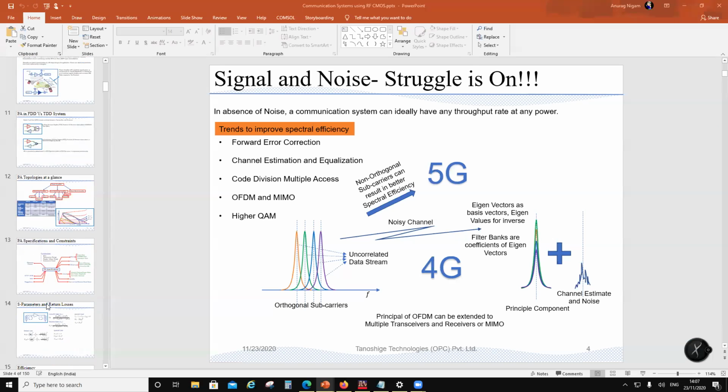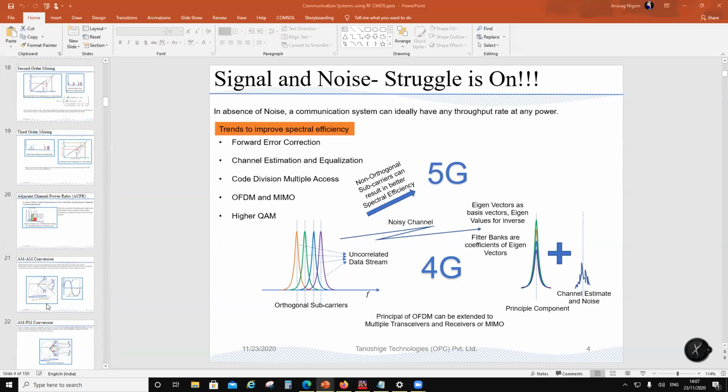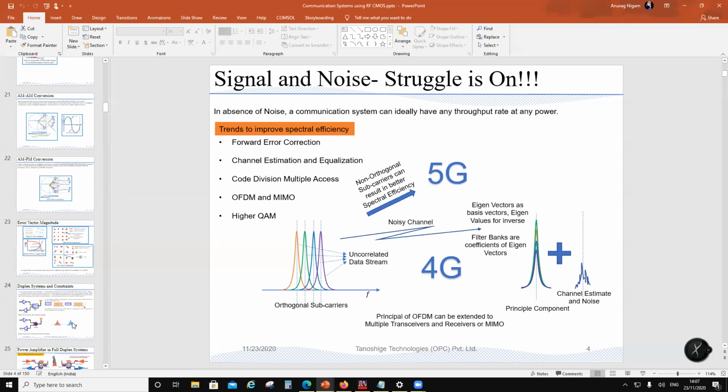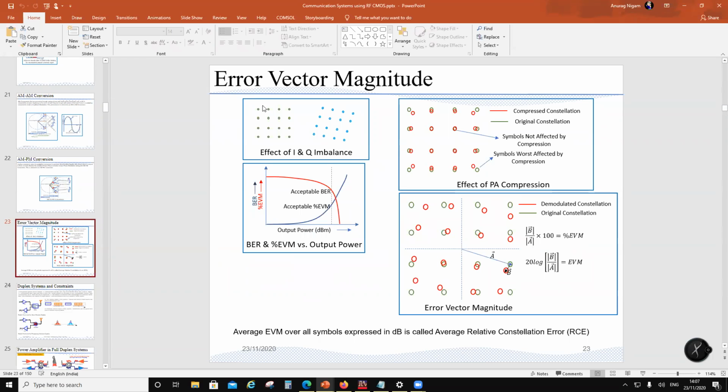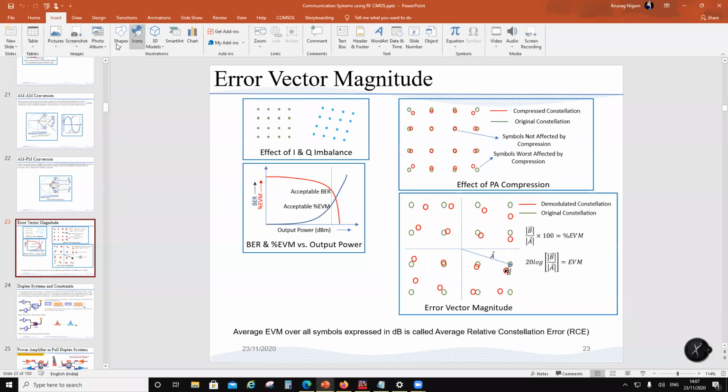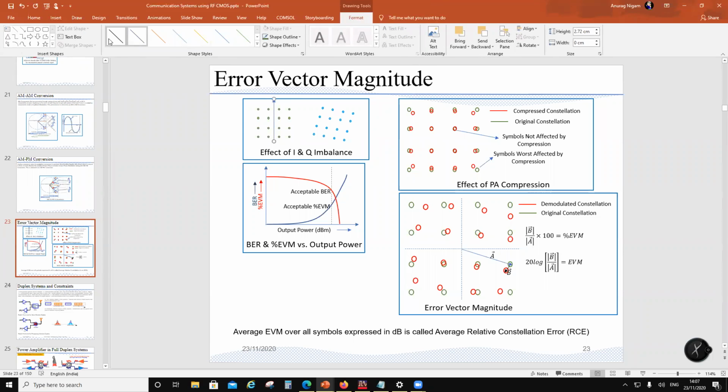If I bundle 4 bits together, let me just skip to what this will look like, like here, for example. Okay, so what you see over here is QAM 16. This is a phasor representation. Let me put one vector like this, this is Q, and the other vector like this, this is I. The center represents 0 amplitude and 0 phase. Phase is not defined at the center.